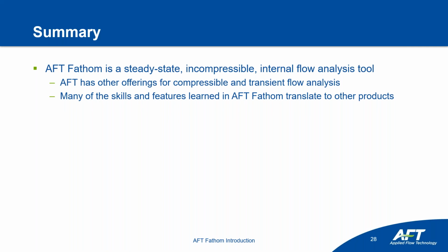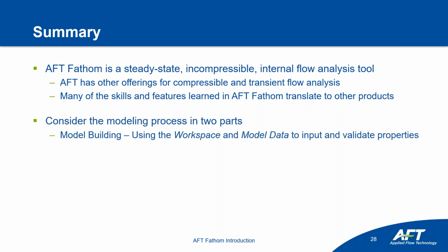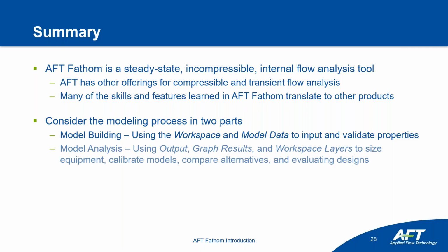So if you have a compressible project that comes up, if you are a competent Fathom user, again, all of those skills will translate to an AFT Aero project. We reviewed the model process in two parts, really. The first being model building, looking at the workspace and model data to input all of our properties and then double check them before we perform our analysis. Where within analysis, we can look at output for tabulated information, graph results for profile graphs and pump versus system graphs, and then also using workspace layers to associate our input and output with our objects or to color code it based on those parameters.